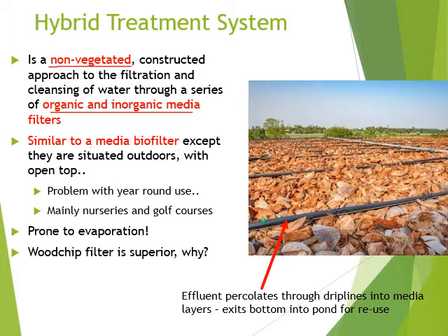So it's very similar to the media biofilter or even like the wood chip biofilter. I mean, these are all variations on the same theme, right? The idea is that you have a large pit, you percolate your water through these trunks down through the media where your biological activity does its thing. The variation, of course, is that this is using a media type filter out in the open, but it's not covered with gravel and slag like a biochip filter.